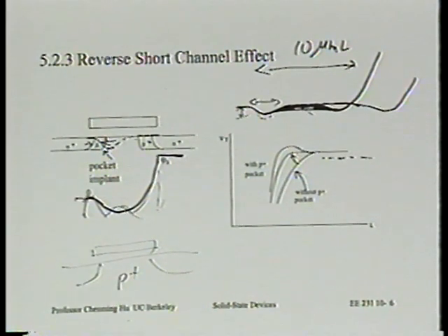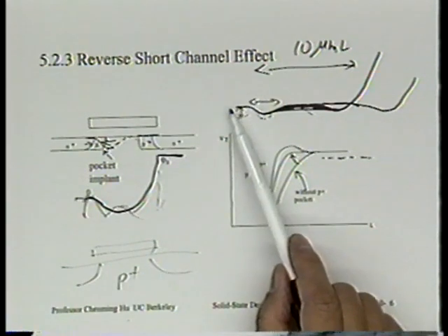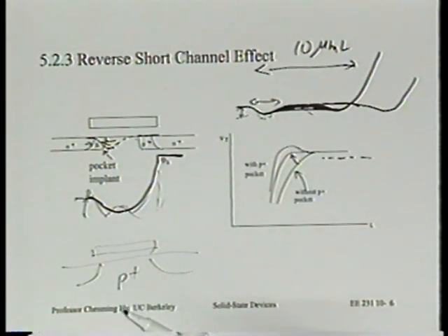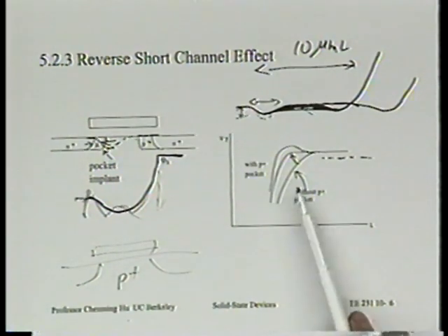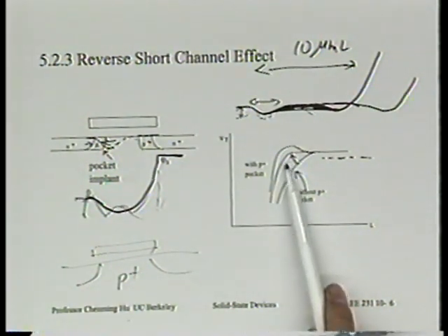Could you perfectly control the doping profile? Assuming you may. I think if you could perfectly control the doping profile, it's just like making a filter that doesn't leak. That answer is correct. All right. So you may want to think about this to see if you understand what that means. And particularly if you think of this as 3 transistors in series, would that ever be possible? Would it ever be possible to pick 3 transistors with 3 thresholds such that it gives you a certain profile? All right. And then you can think about the more subtle picture that I ask you to think about, and see if it's possible for you to have a case where the threshold voltage does not really increase, but it will delay or minimize or reduce the roll-off of the VT.